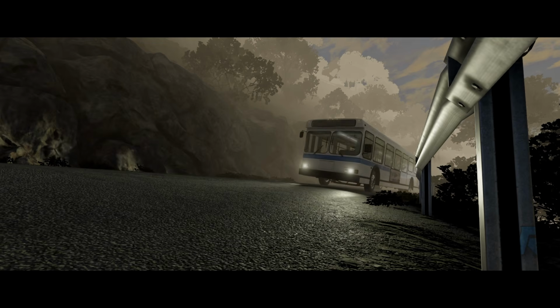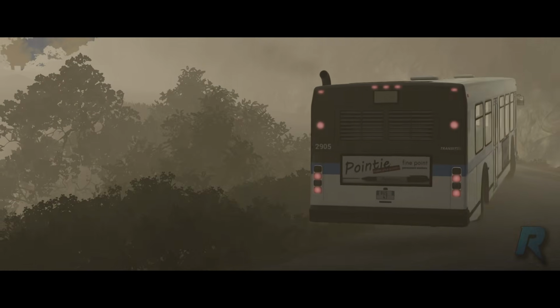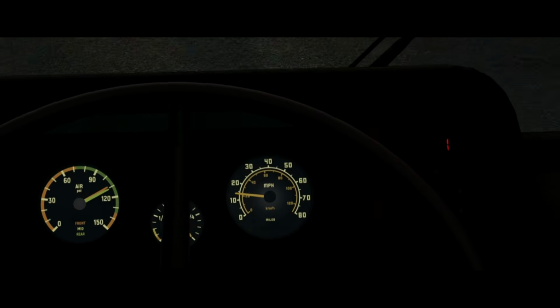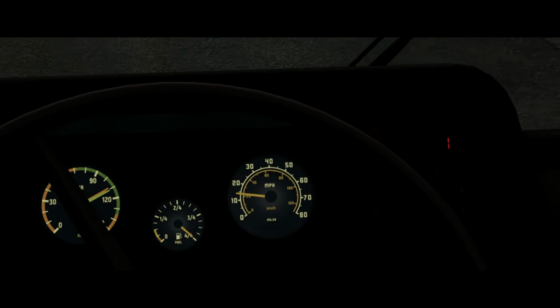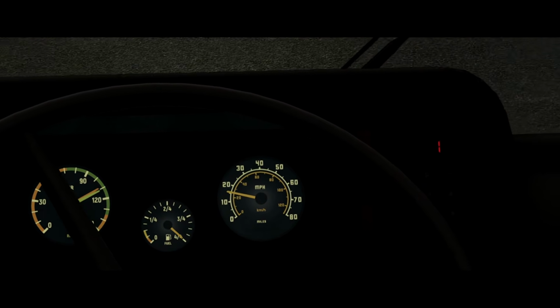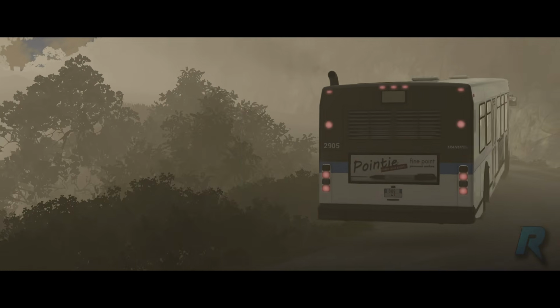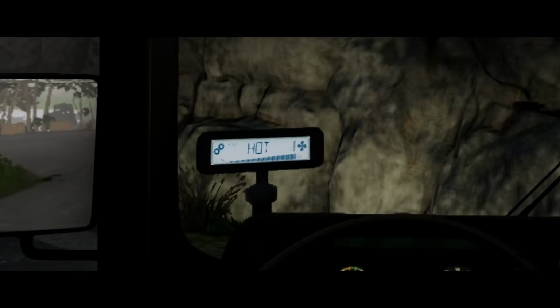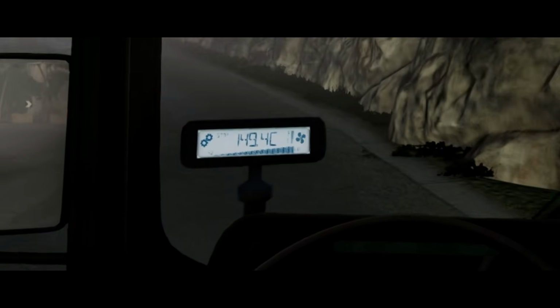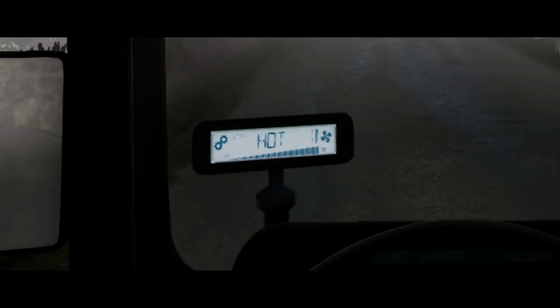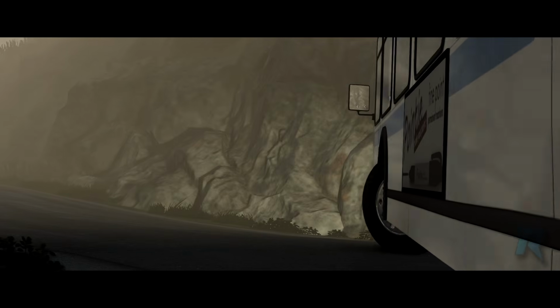As the bus kept climbing higher, the mountains got steeper, and the engine worked harder. The harder the engine worked, the more heat was dumped into this already scorching hot oil. The bus began to slow down after corners, accelerating slower, but with higher engine RPM. As the engine was revving higher and the bus moving slower, the transmission temperature was in its danger zone, but the driver didn't care.